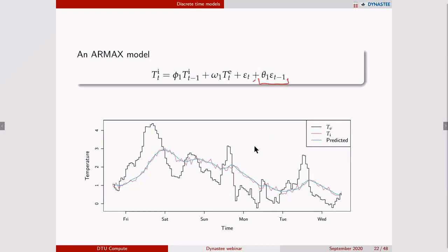And if we do that and fit the model, now it's a little bit more complicated to fit the model, and we actually need a Kalman filter to do this. Then what we get is this: the prediction is this blue smooth line, and now we actually really separated the noise from the actual state itself, or the internal temperature itself. So that's what the Kalman filter does, that's why it's called a filter, because it separates the noise and the signal.